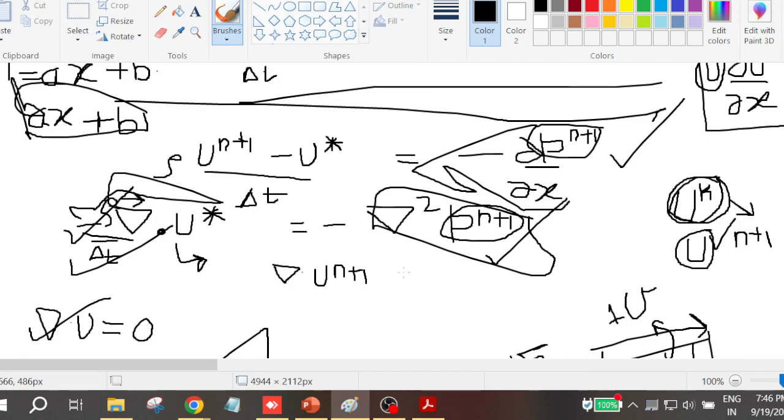You should learn the software in general as a whole, just like how you learn ANSYS and all, although OpenFOAM is completely different, but you can learn it on that level by just watching videos, okay. The second step is when you want to extend the OpenFOAM solvers. So you have something like icoFoam, pisoFoam, incompressible solvers, and PISO algorithm based methods and all. Now when you want to extend those methods, you will get into coding, and that happens very rarely. And if you want to have some multiphysics, okay, if you want to model a transport equation, you will get into coding. Now the coding is C++ in OpenFOAM, okay.